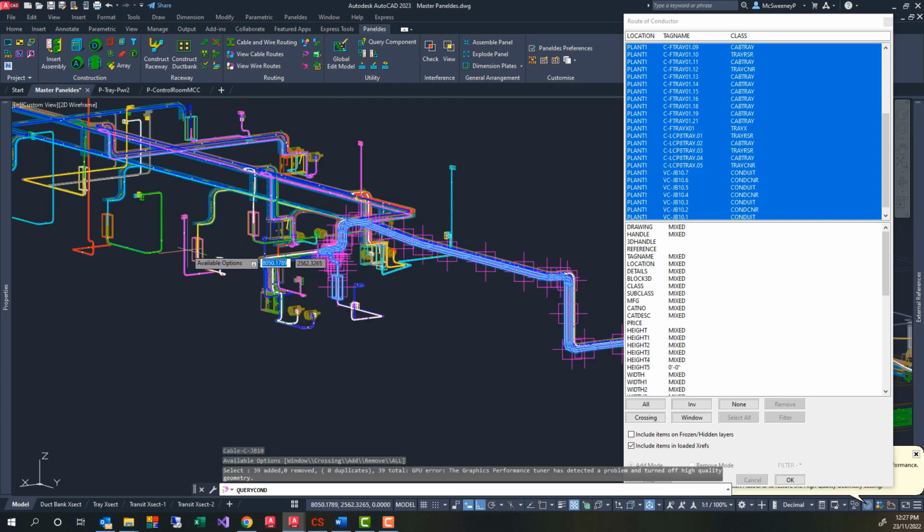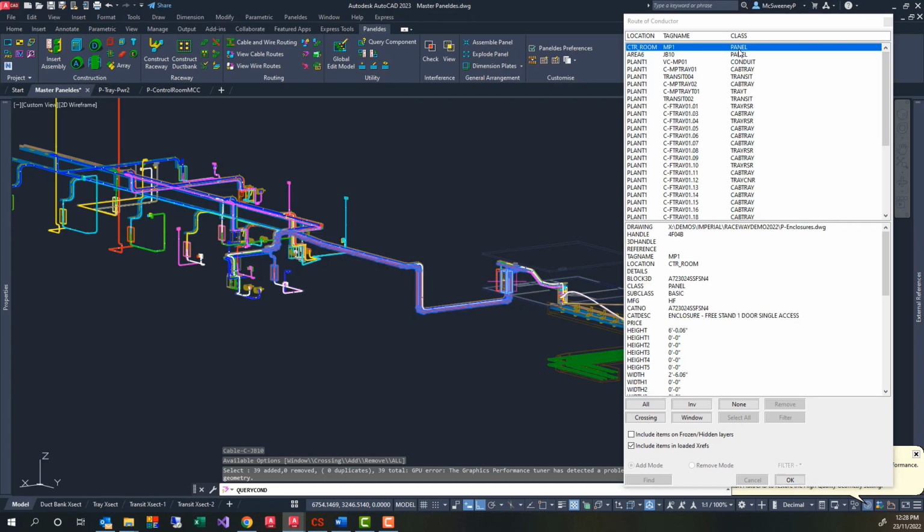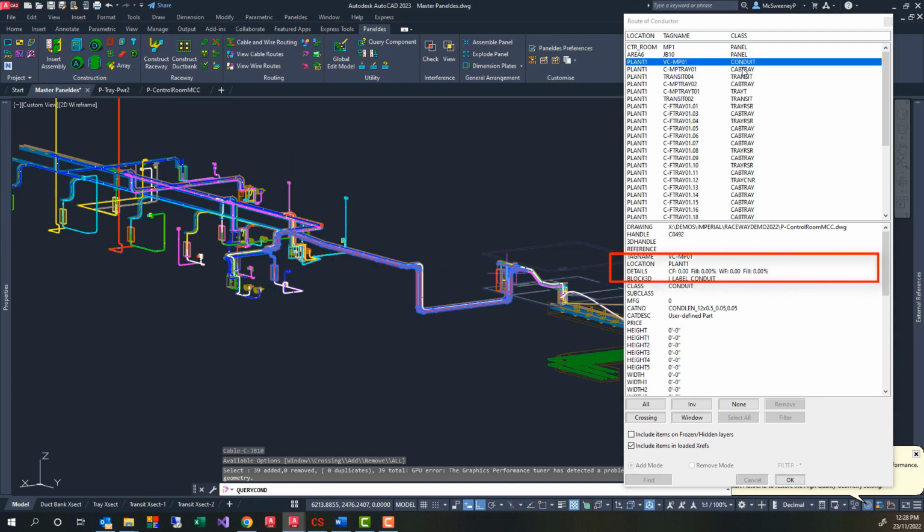My route visibly looks excellent. There is no short path, so I have no reason to check it further. However, if I did suspect it had taken a wrong turn, I could step through the trays along the route and examine the filling and any warnings on the trays. An engineer only needs routing diagnostics to understand why a route appears to be wrong. As I step through each tray, you can see the filling of that tray. The tray is also highlighted with a magenta crosshair on the model.